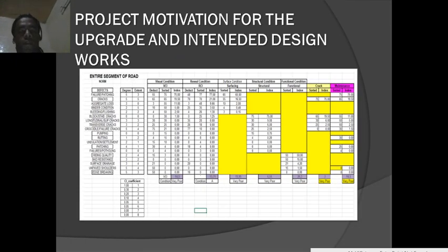As mentioned before, the road is in a very poor condition because of the purple lines, which state that all the road in purple is in a very poor condition. As a visual condition assessment spreadsheet that I used, you have the defects on the left, such as failures, cracks, aggregate loss, etc. And then right next to it, we have the degree and the extent. Now the degree and extent is what we use to evaluate those defects that are found in the road.